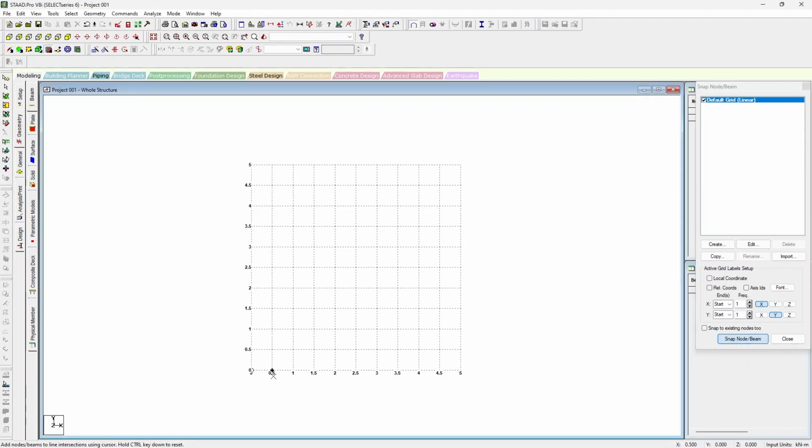So now you just click there and we can start at our origin, which is 0, 0. You click there. Let's assume the height of our column is 3 meters. You can click there and click on escape. Now we need to create another column which will be supporting on this other side. You click here, we have a span of 3 meters from 0 to 3 meters and then a height of 3 meters. Click there and you're good.